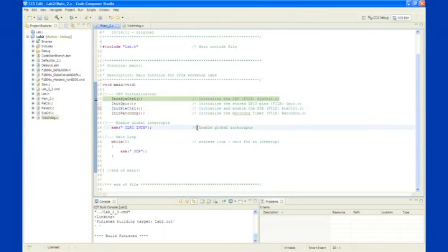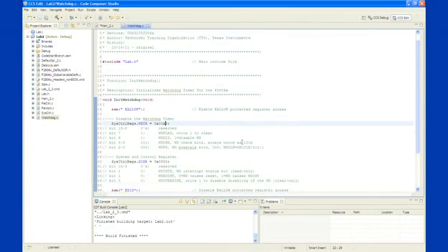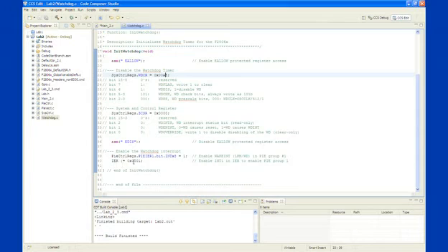In main, a couple of things we need to notice down here. Right here is the code used to enable global interrupts. And if we look in our watchdog, we will see code on the bottom here which enables the watchdog in the PIE group. And the next line here enables the core interrupt line 1, coming in from that group. So the next thing we'll do is we're going to modify the watchdog to generate, rather than a reset, an interrupt. So I'm going to change that to 2. And we will save that file off.